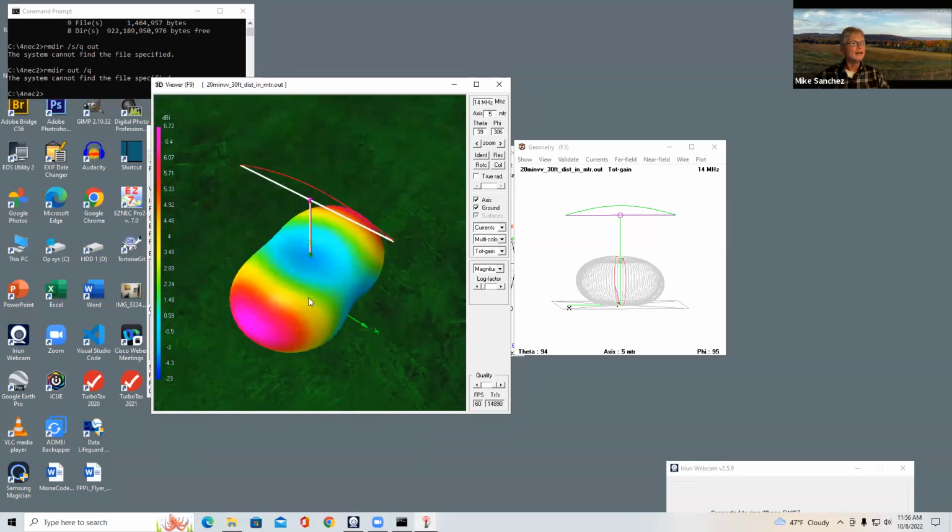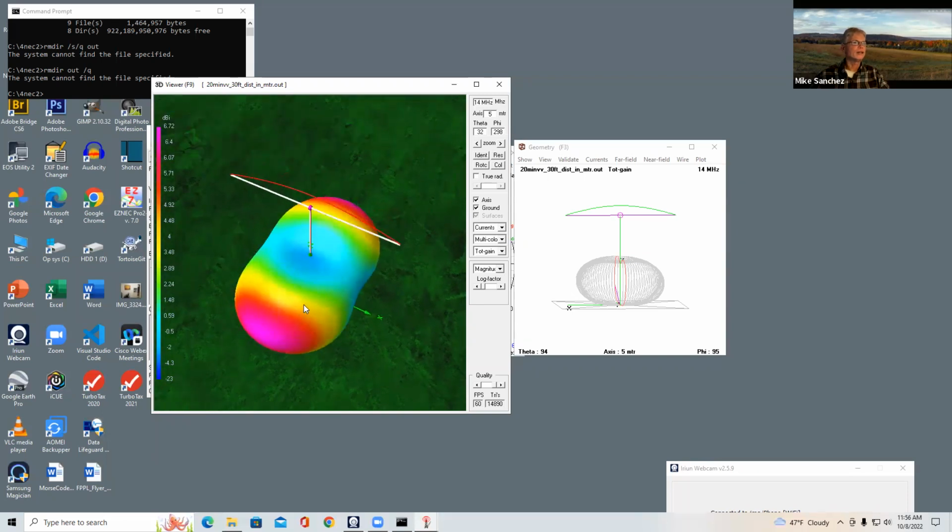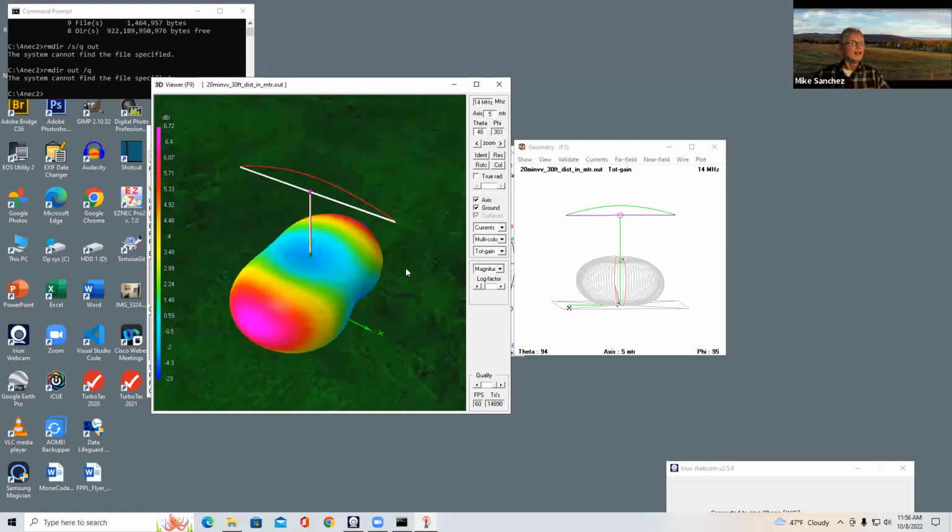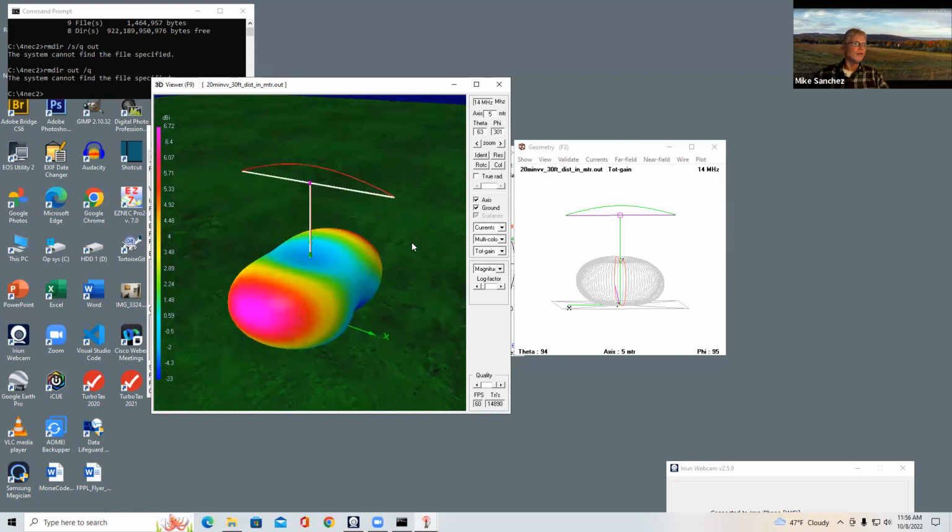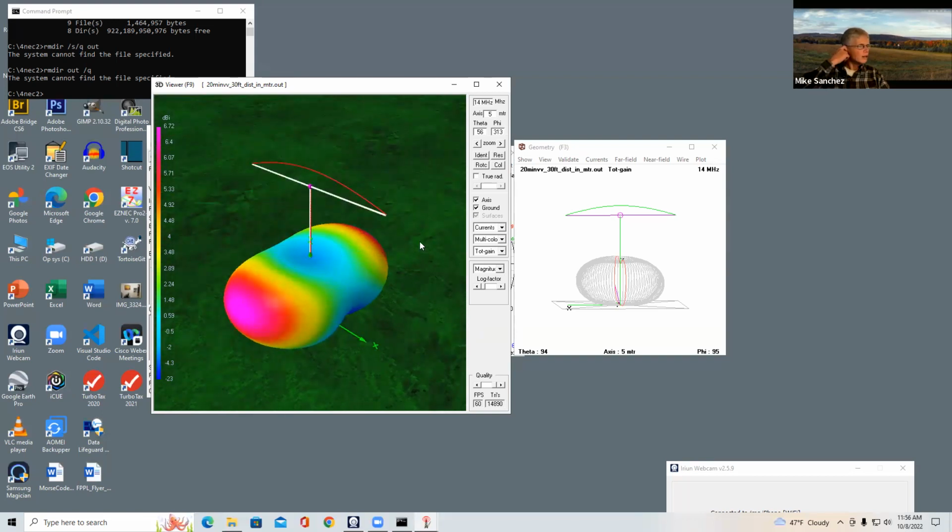So my antenna is oriented in this direction, which sort of points north. Japan is over here, off the null of the antenna. So the lowest gain is this side. It's not zero, but it's some teeny little gain. About 6 weeks ago, I was using FT8 one morning, and a Japanese station came in on FT8 on the side of my dipole, no lie. But that doesn't happen very often. However, I get Europe routinely, I get Mexico, all with this nice little dipole.